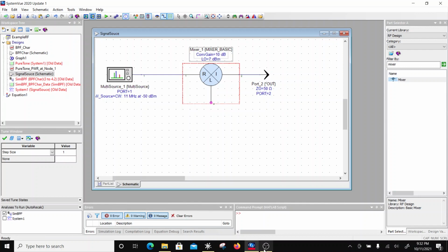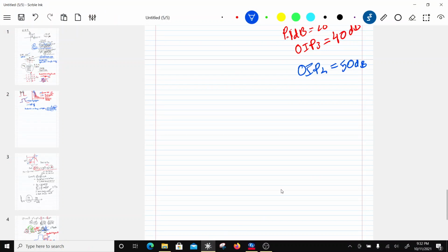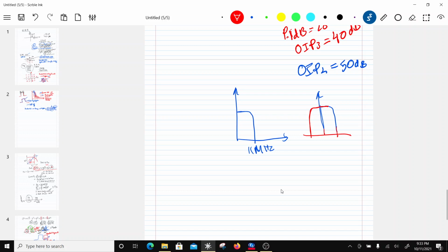So for example, let's say that this is the baseband, and I have this information up to 11 megahertz. When I upconvert it, I am going to get the plus side, and I'm also going to get the minus side, and there is no way you can suppress this out. So usually we are going to transmit both sides, right?